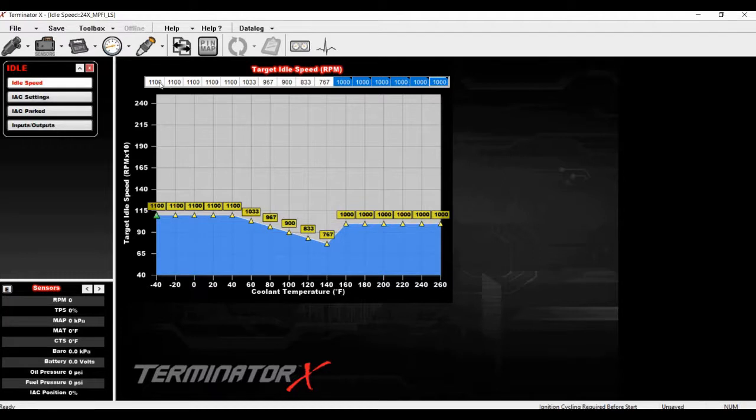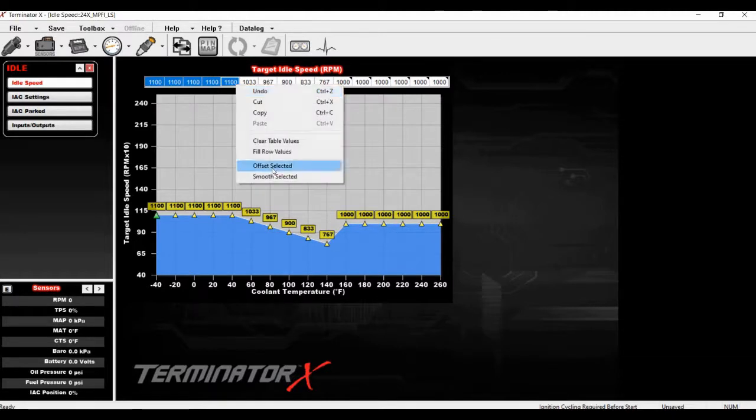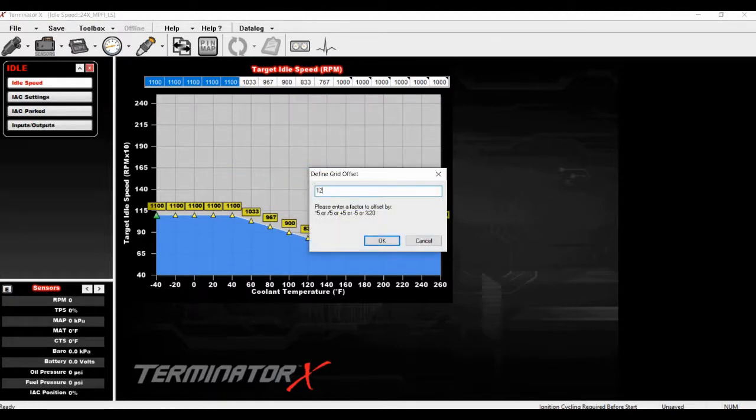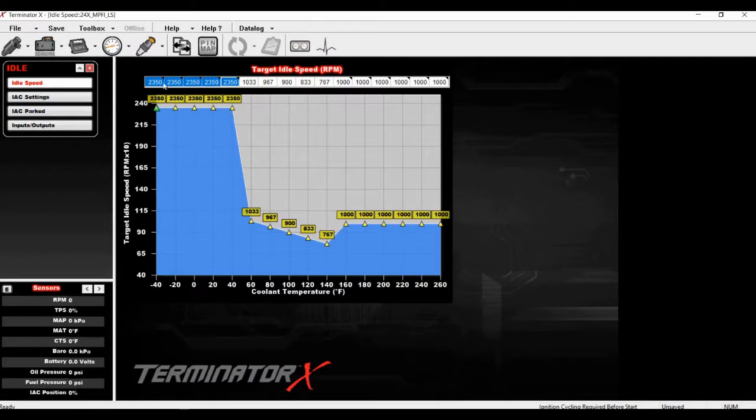And then, same thing applies to whenever you're starting the engine up. If it's cold outside, don't try to idle it at the same speed that you want to idle whenever the engine's hot. That's what fast idles are for on your carburetors in the 50s. If they had it, you can have it too. Let's just go ahead and make this 1250. Apparently I can't type today. 1250.